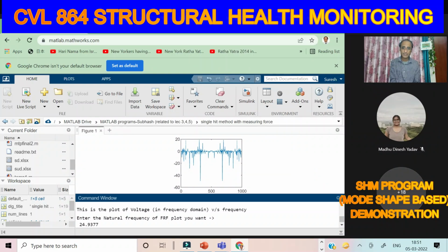See, what was the frequency in the case of the undamaged beam? It was 34 something. And you see here the major peak. After damage the frequency cannot increase, it will reduce only. So some of the peaks were 79, 44 something. We ruled them out and we have chosen 24.9377. But whether this is correct or not, we have to see the plot first.